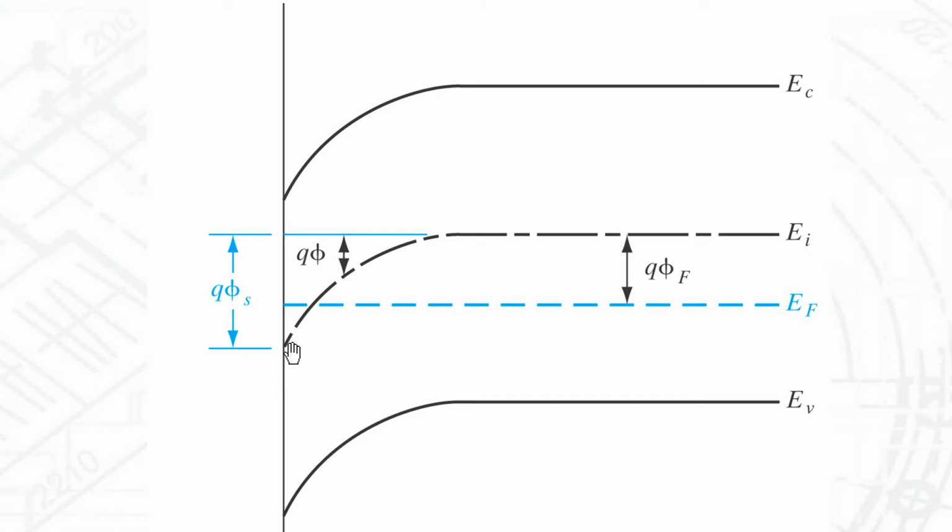That's how we know that the material has been inverted. I just showed you the physical model, where I said the electrons get pulled in, so you have an n-type material. The energy band model is saying the same thing, except in a different language. EI is below EF, which means we have a low hole concentration and a large electron concentration.